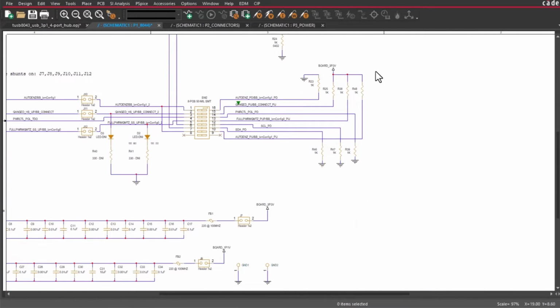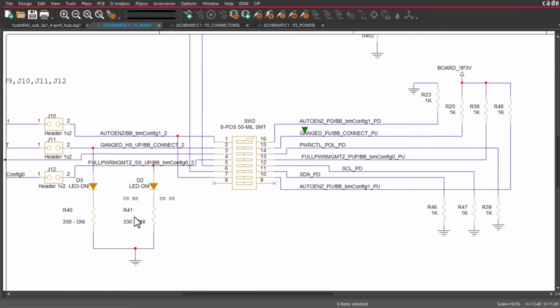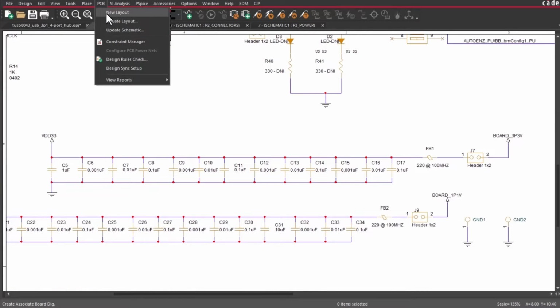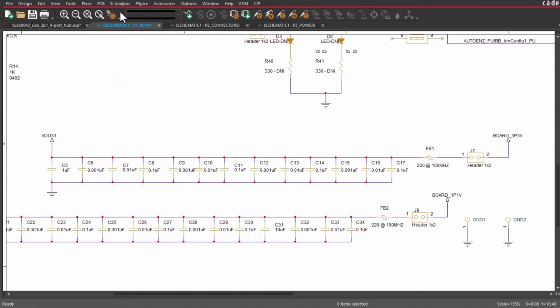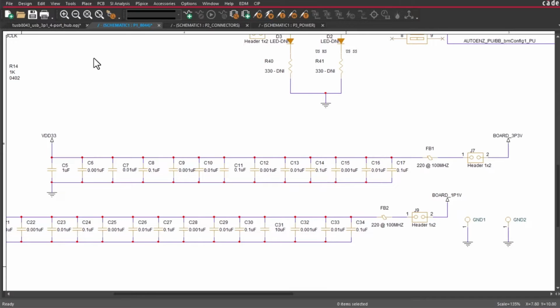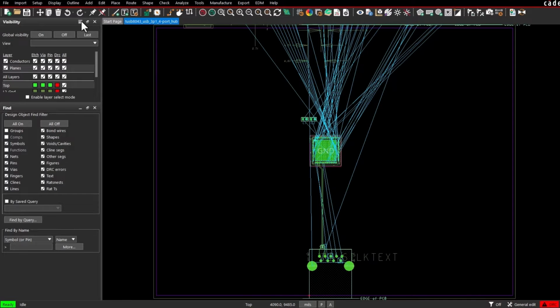Once you're done capturing the schematic for the entire design, connecting them with the wires, validating and checking there are no errors, even setting your constraints in the schematic, combine all of your information like your component footprints, the 3D models and everything, and then generate what's called a netlist. This netlist will then be used to export your schematic concept to the printed circuit board in the mechanical phase.